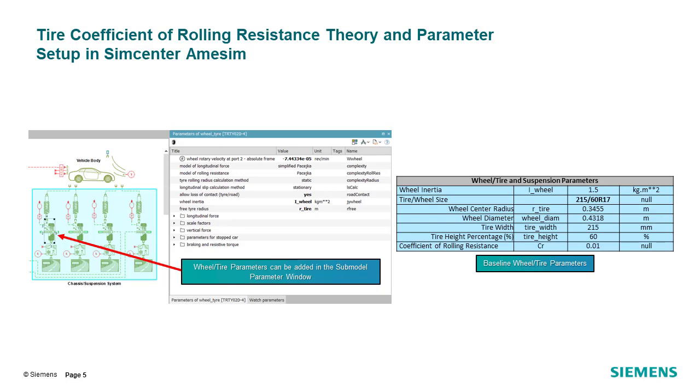Comparing the rolling resistance force provides a direct way to compare tires of the same size, as well as an accurate means of comparing different tire sizes to one another. Comparing rolling resistance coefficient allows comparing tires within a single size and does not allow comparing tires of different sizes. Larger tires generally have a lower rolling resistance coefficient than smaller tires but generate higher rolling resistance forces at a given speed.